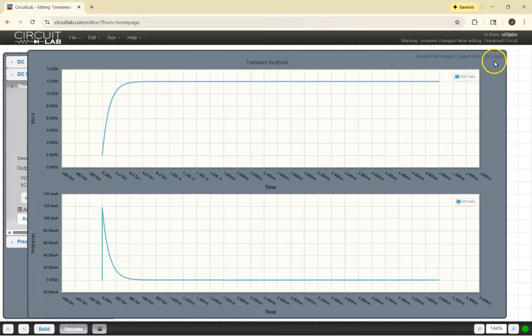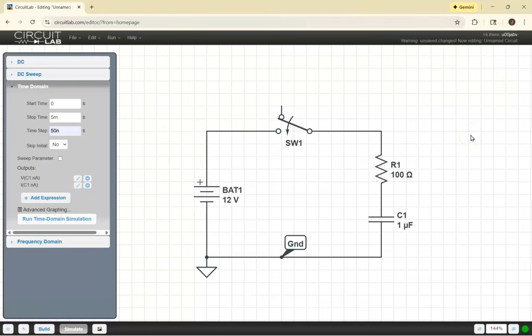If I were to try to watch this with my digital multimeter, in either case, what I'm going to see is the voltage will go from basically 0 to 12 almost instantly. So this is one of the advantages with an oscilloscope. I can watch something that's going to happen very quickly. I can view that with respect to time.